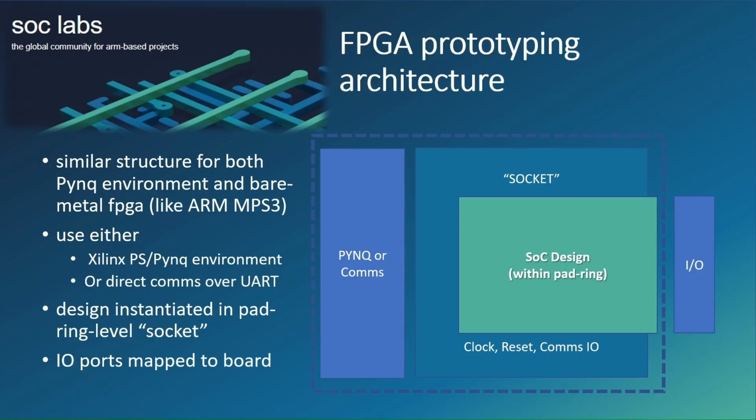The structure for this then, so we instantiate the full SoC just below the pad ring level into a socket, which has got clock, reset, communications. Then for downloading code, downloading vectors, we've either got the PYNQ environment over the AXI. For the ARM MPS3 board, we've got the UART comms, and all of these go into our ADP, our SoC debug controller.